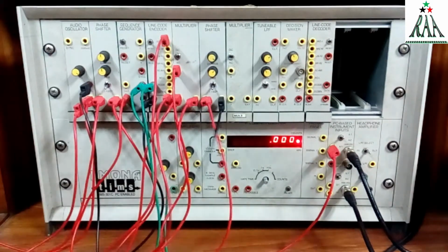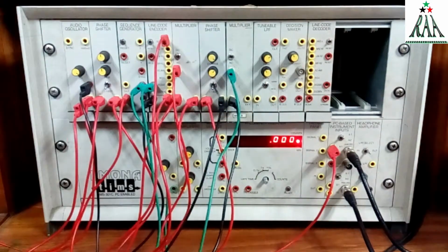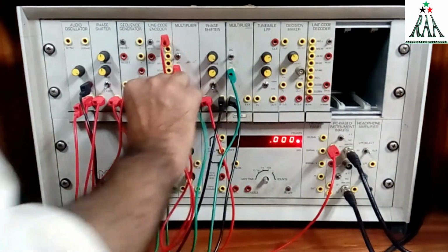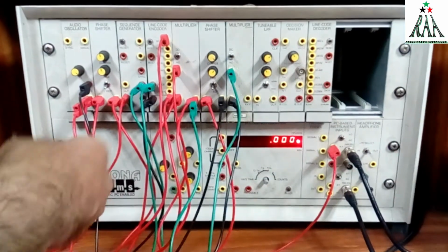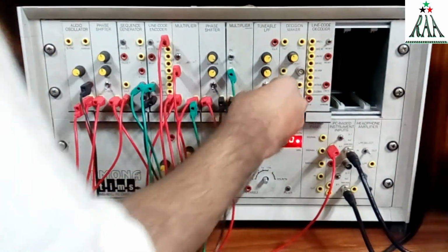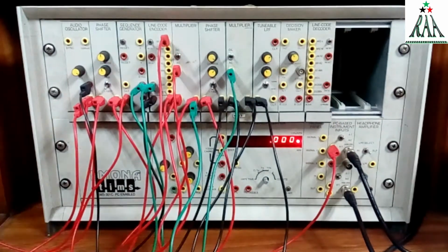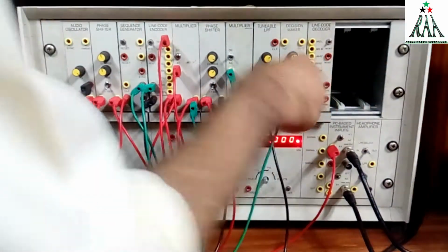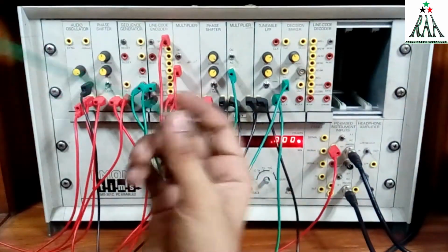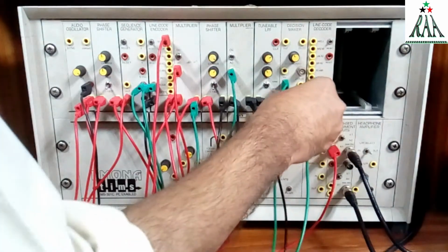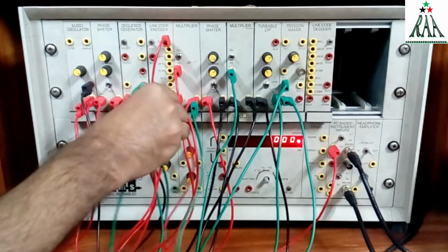and give its output to a multiplier, and one of the inputs of the multiplier will be the BPSK signal, and the output of the multiplier will go into the LPF. The output of the LPF will be given to a decision maker, and the bit clock of the decision maker will be taken from the line code encoder.